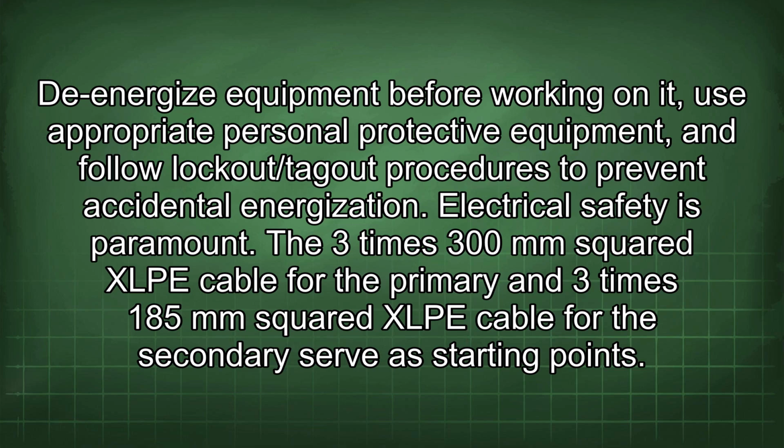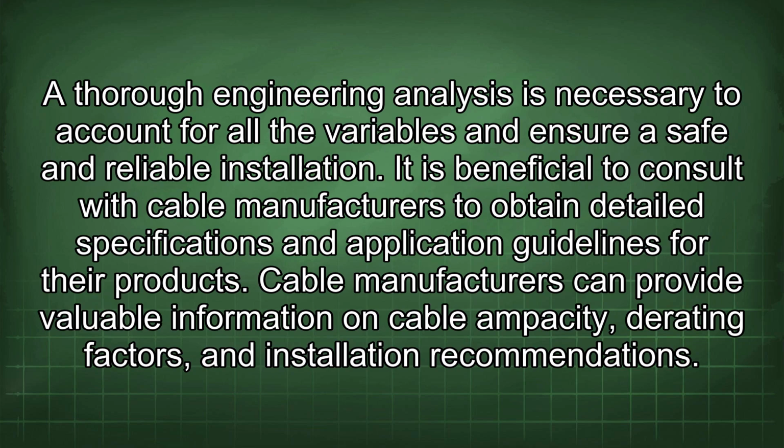Electrical safety is paramount. The 3x300 mm² XLPE cable for the primary and 3x185 mm² XLPE cable for the secondary serve as starting points. A thorough engineering analysis is necessary to account for all the variables and ensure a safe and reliable installation.